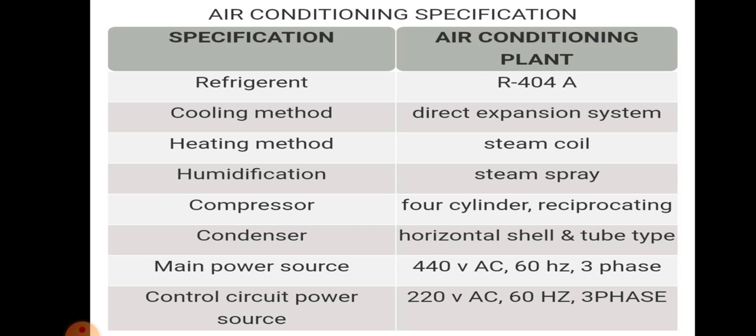The compressor is 4 cylinder reciprocating. Humidification is steam spray type, and heating method is steam coil. Cooling method is direct expansion type.